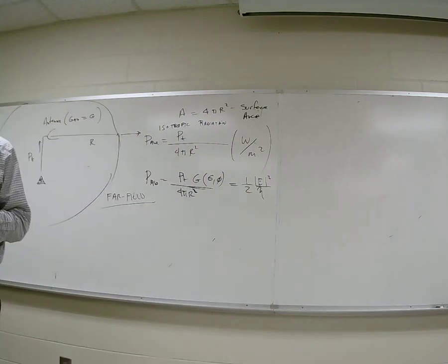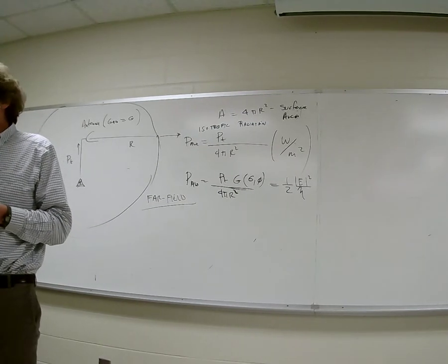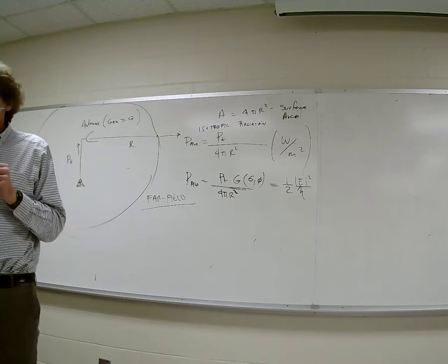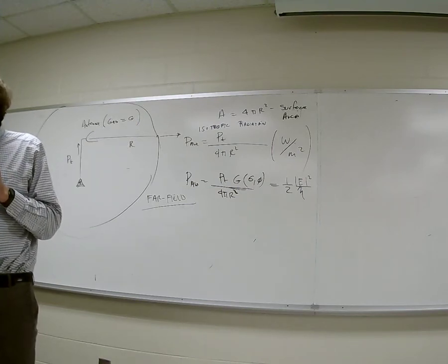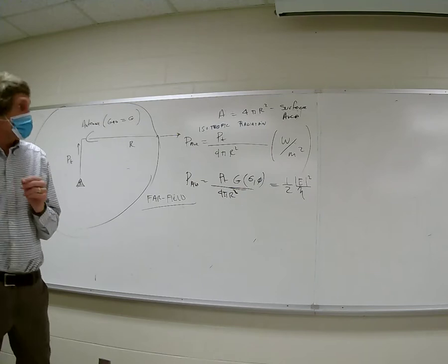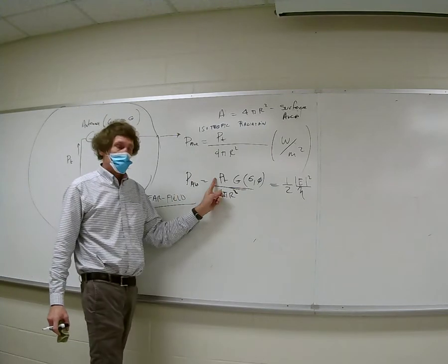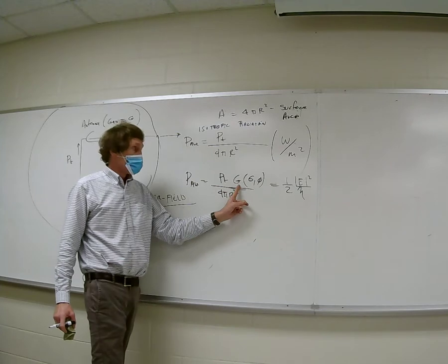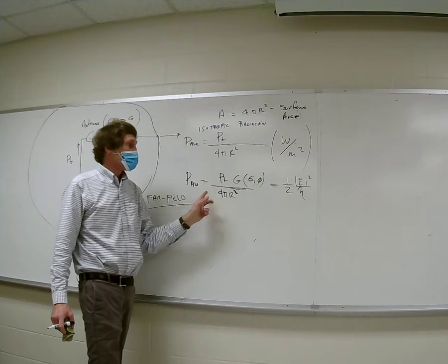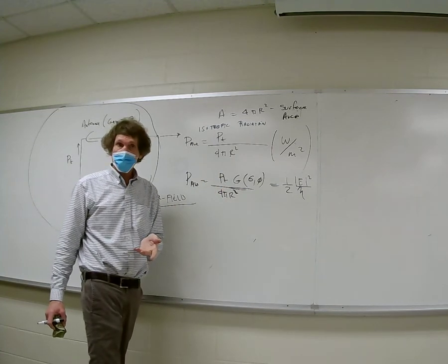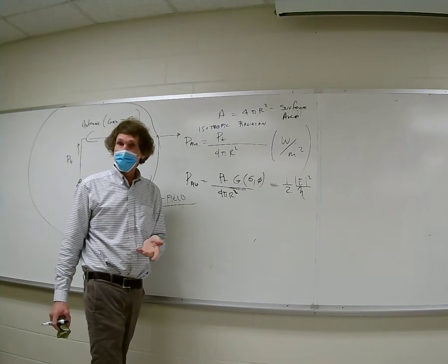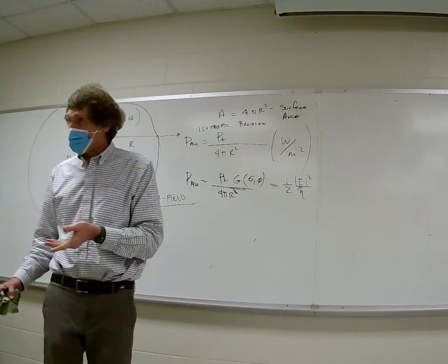How many remember that? All right. If you don't, don't worry about it, but this is the standard propagating wave's power density. It's always proportional to the E field squared. It's multiplied by 1/2 because that E field would be the peak value of the E field. And it's divided by the intrinsic impedance of free space, okay? Which means if I know the transmitted power, the range, and the gain, I can get the E field, right? I set these two equal together, solve, and take the square root, and I have the E field magnitude. Do you all agree with that? Can I get the H field for a propagating wave? What is the ratio of E to H always if it's propagated?